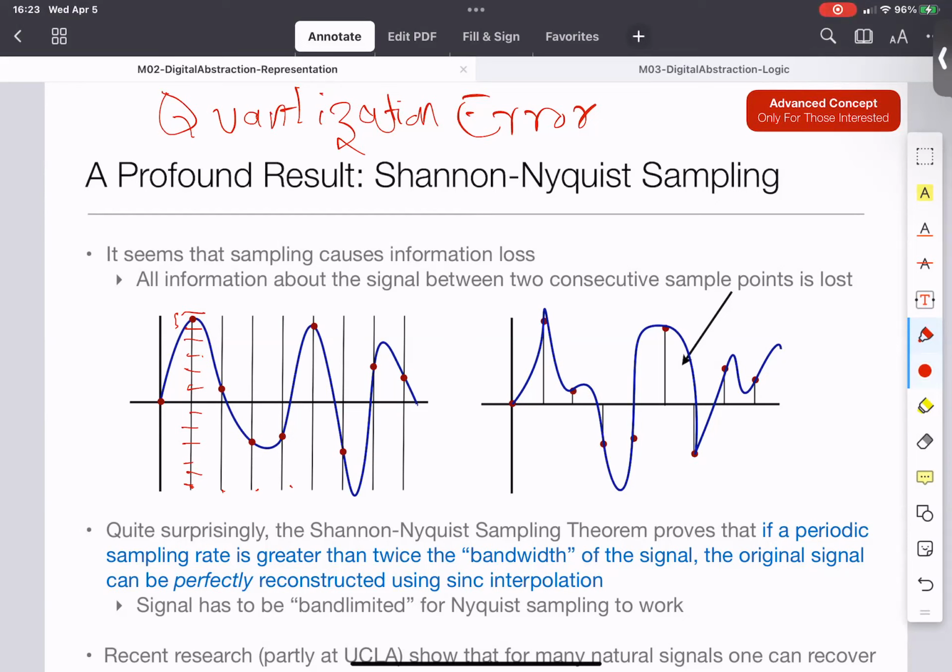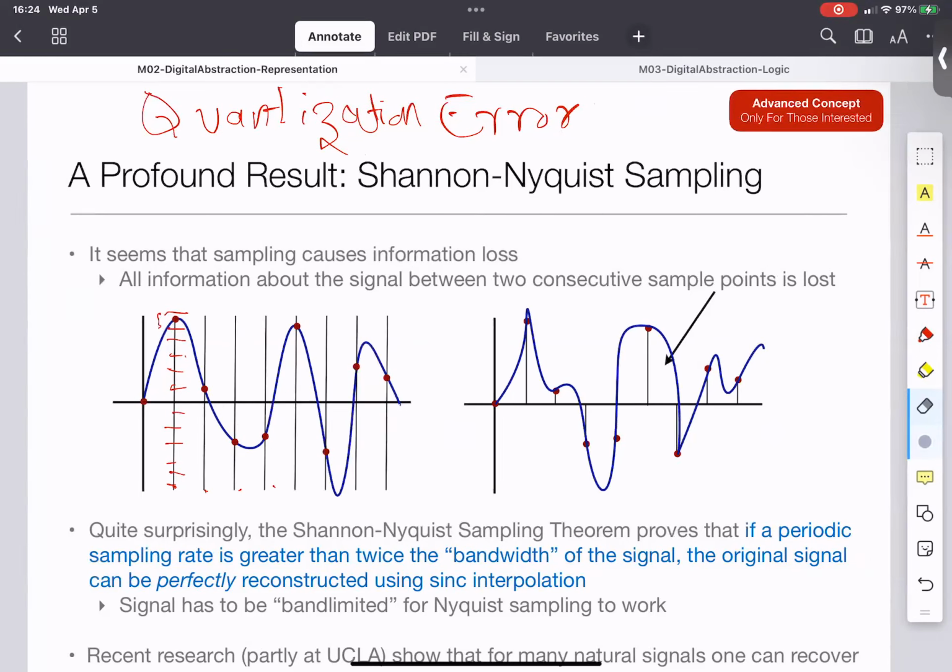That would cover any place on Earth, for example. So applications differ, and therefore both these things, how often we sample and how many bins we divide into, are a function of the application. Once we have done that, as a digital system, every so often I'm getting a value out of a discrete set.